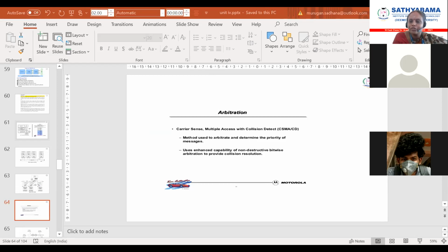How do we use the UPS? Do you know how the UPS is connected? Anyone tell me how it works? It consists of a rectifier and a battery circuit, ma'am, such that the incoming AC voltage is converted into DC with the help of a rectifier. It is stored in the battery. When the power goes off, the circuit will convert the DC to AC, and it will give it to the loads.